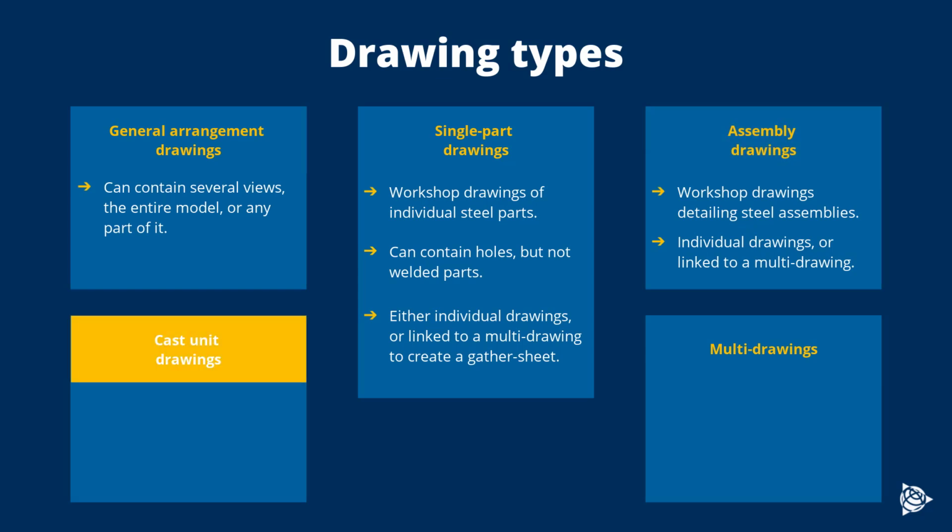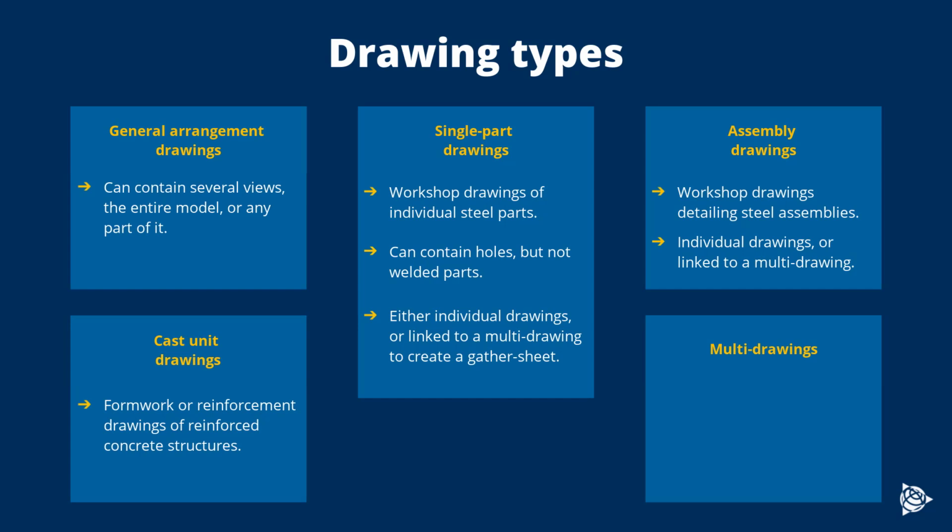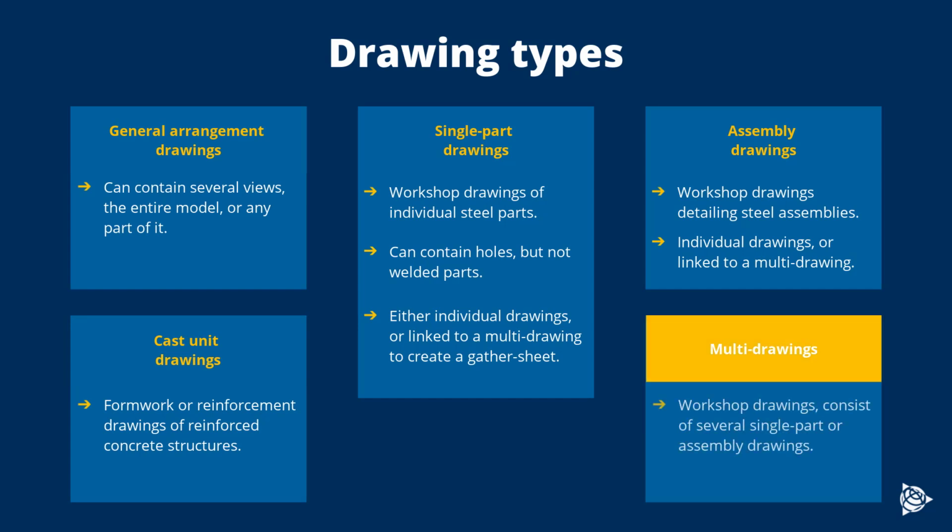Cast unit drawings are formwork or reinforcement drawings of reinforced concrete structures, such as foundations. Multi-drawings are workshop drawings, which gather together several single-part or assembly drawings on one sheet. The configuration you use determines which drawings are available.